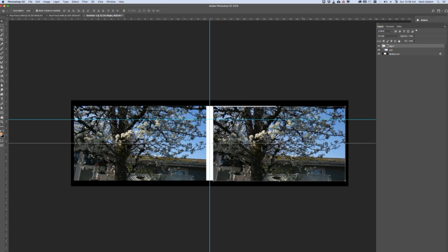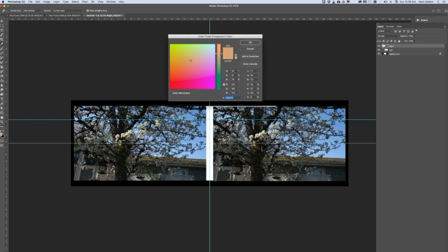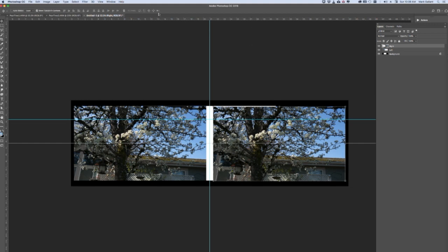Any offset will be masked by framing. Set the convergence by looking at the composite through the stereogram viewer, as we've done earlier in examples. Then select both images to move in unison to final centering. Create the frame cutout guides and make the frame as we've already done earlier, and then save your work.